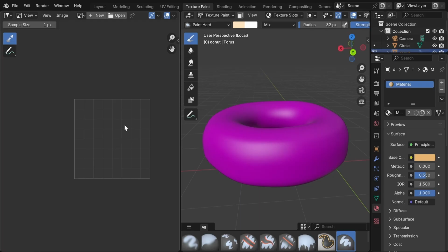So when you paint on the image, it appears correctly on the 3D model. Alright, switch to the Texture Paint tab. If you try painting right away, you'll notice nothing happens. You may get a warning, Missing Textures Detected. That's expected. UVs define placement, but we haven't created an actual image to paint on yet.